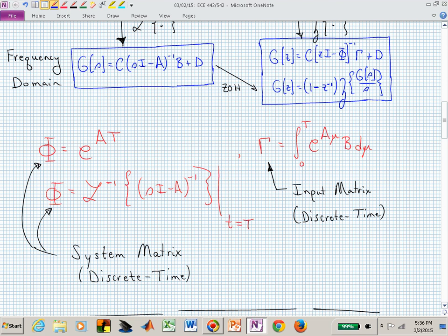But then you would have 100 inverse Laplace transforms. If it's an A matrix that's 10 by 10, you have 100 potential entries in that, and it's dependent on this variable S. But those are just your standard inverse Laplace transform techniques. You'll now have those in the time domain. You can put those into a sampled or into the e to the capital AT form by now replacing little t with capital T, and you will then pick a capital T appropriately.